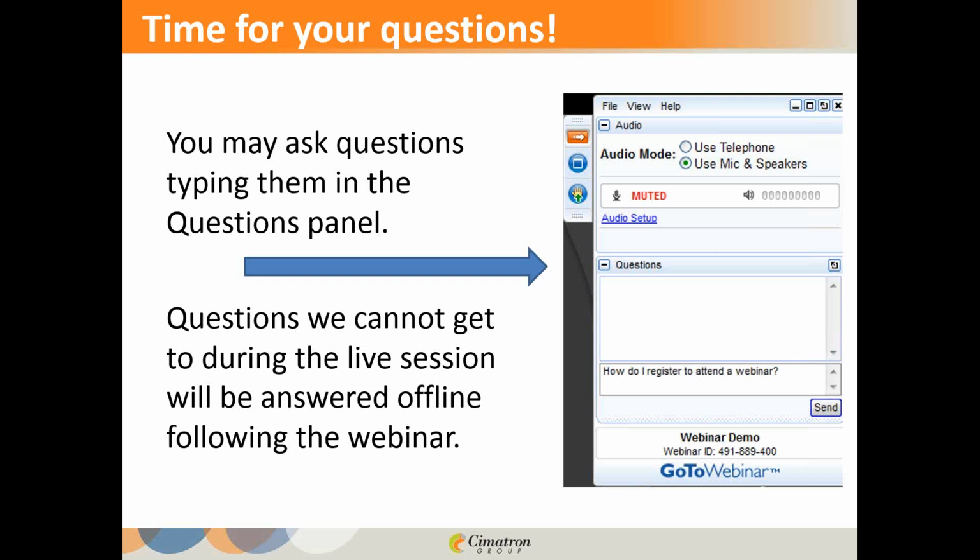Well, in that case, it'll show you what's going to happen, and you can take this information back to the customer and say, look, we know with our experience and what we're seeing, you can't form the part the way you've got it designed. You have to give some consideration in these key areas, such as the radiuses. It is what it is at that point. The material is going to act like the material. So you can make adjustments to the gauge thickness, the material type, all that, but that's the kind of thing you have to go back to your customer on to get his approval anyway.